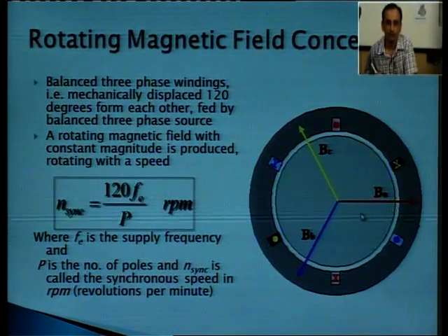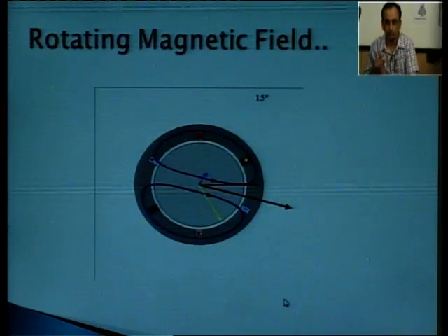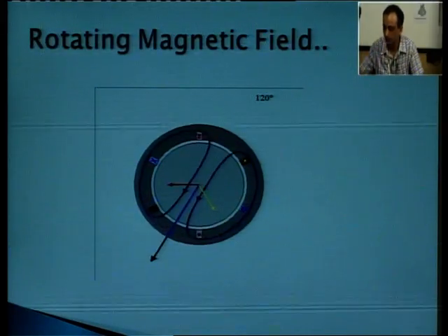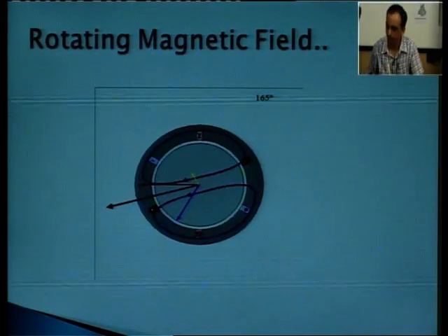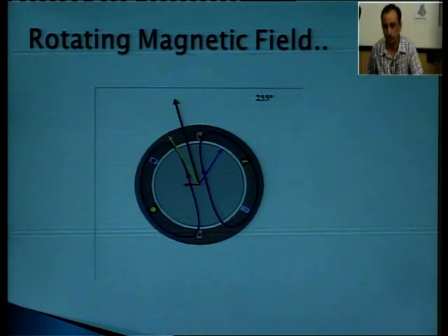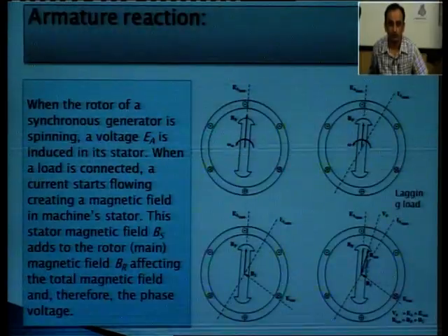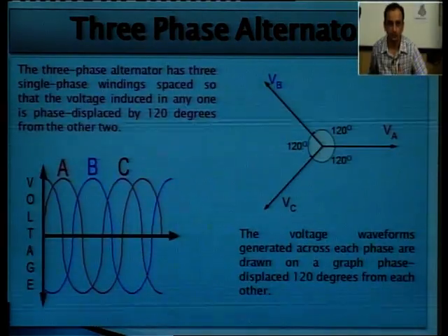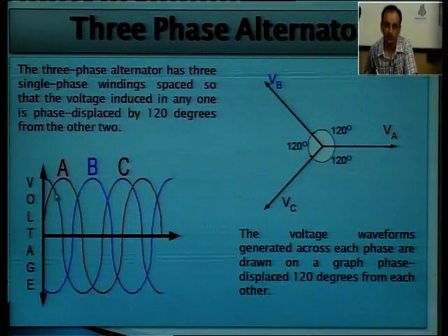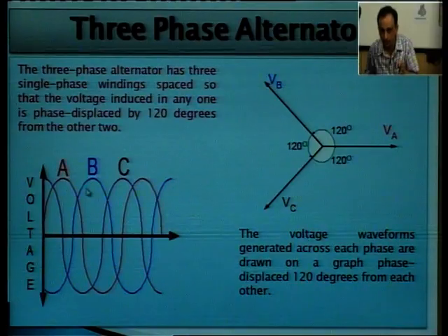Here you can see that the flux is changing after every instant, because the supply that we are applying is varying with time. We have 3 phase windings, and in this case, first phase A, then phase B and then phase C attain their peak after every 60 degrees.